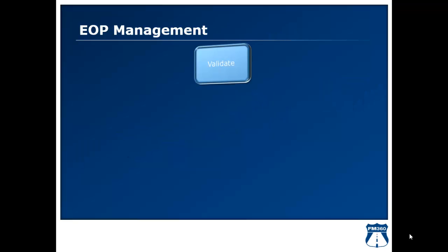EOP management. One of the first steps in that is to validate your procedures once you have written them. That is very difficult to do in a live facility. So what I often do is we'll walk up to these systems and do kind of a mock run where you're not really activating switches or whatever, but you're at least going through the steps.